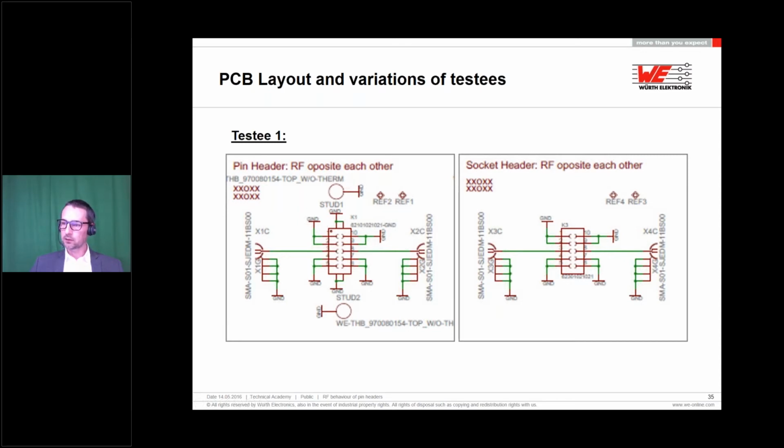Then it goes up to its counterpart on the top PCB and goes out to the according coaxial connector. And we do exactly the same on the opposite pin here. So that's the important point: this is the closest distance between the two pins. This will not have a lot of impact on the insertion loss or on the matching, but it will definitely have impact on the crosstalk.